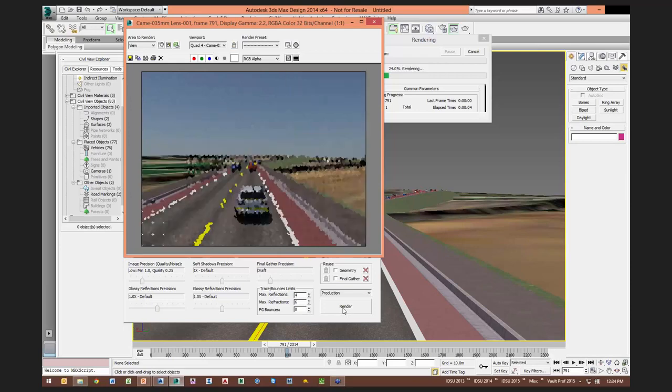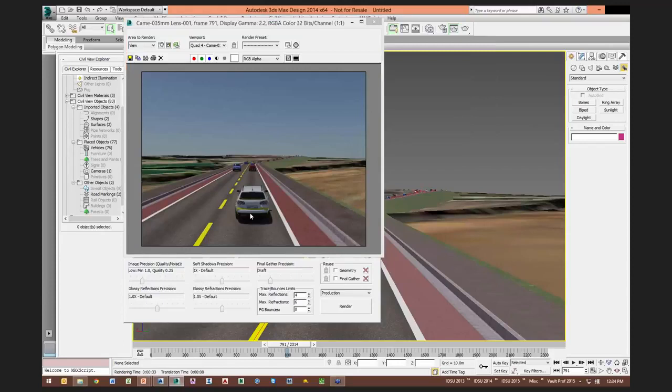So when I'm working live in the 3ds Max model, the quality of the visualization is turned down a little bit, but I can push out renderings and get something that's pretty photorealistic. I have some of these settings like image precision and things like this. I've set it pretty low, and what I get right out of the box with just what I've created in 15-20 minutes is really a pretty nice rendering.